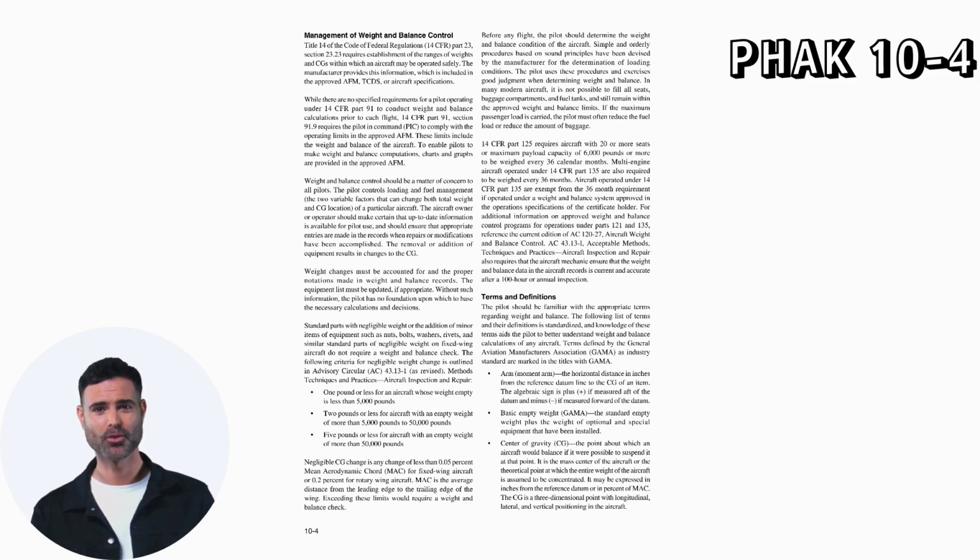If the maximum passenger load is carried, the pilot must often reduce the fuel load or reduce the amount of baggage. 14 CFR Part 125 requires aircraft with 20 or more seats or maximum payload capacity of 6,000 pounds or more to be weighed every 36 calendar months. Multi-engine aircraft operated under 14 CFR Part 135 are also required to be weighed every 36 months. Aircraft operated under 14 CFR Part 135 are exempt from the 36-month requirement if operated under a weight and balance system approved in the operation specifications of the certificate holder.